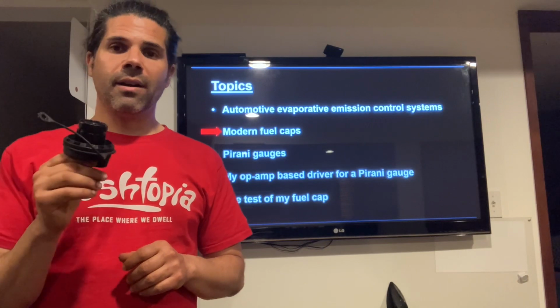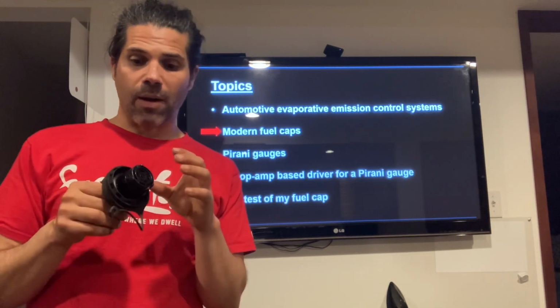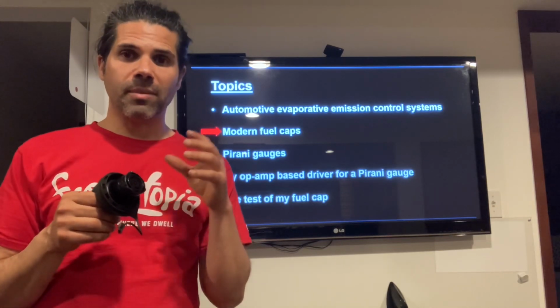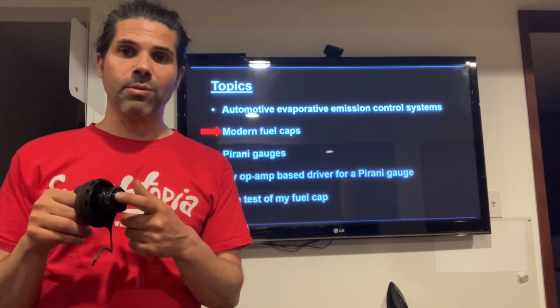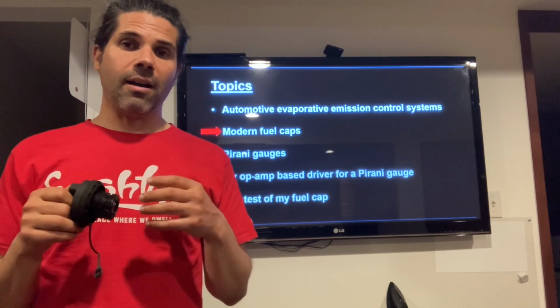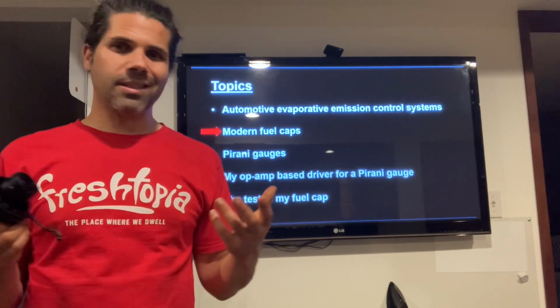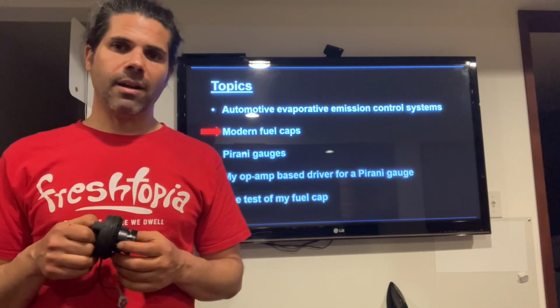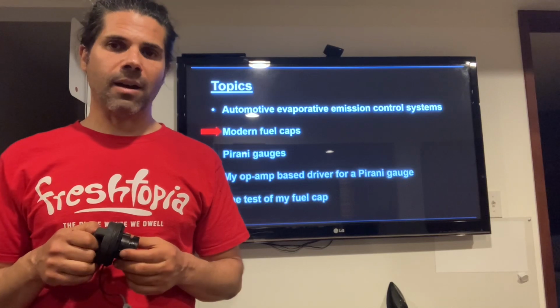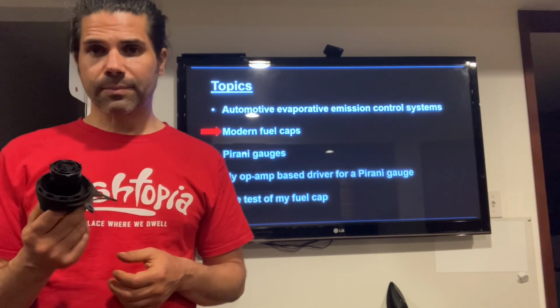This one here is designed to stay sealed, except when a moderate vacuum is seen inside of the fuel system, and then it's got a spring-loaded vent release that vents that vacuum and prevents the vacuum from getting too deep, just in case there's a clog in the vent valve or something. You won't have a problem with your car. It won't stall out on you.